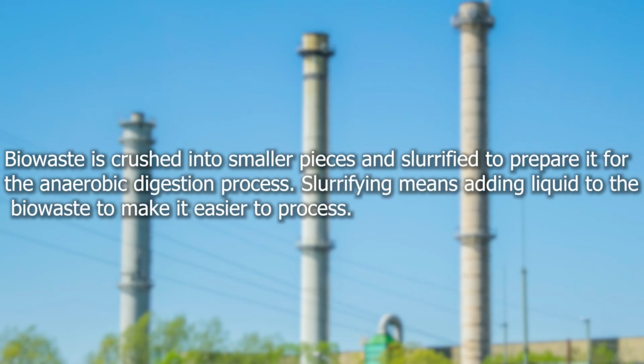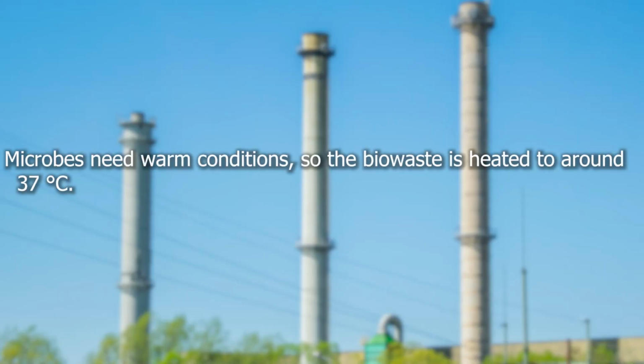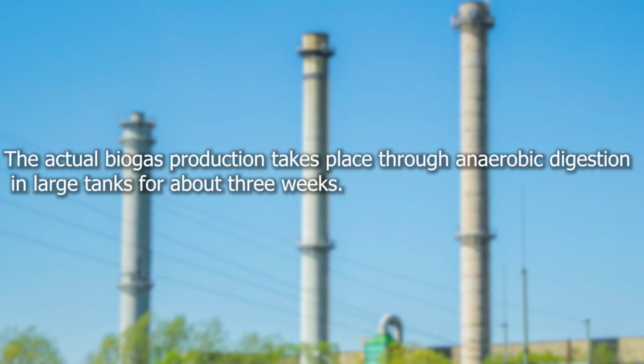The first stage is that bio-waste is crushed into smaller pieces and slurrified to prepare it for the anaerobic digestion process. Slurrifying means adding liquid to the bio-waste to make it easier to process. Second, microbes need warm conditions, so the bio-waste is heated to around 37 degrees Celsius. Third, the actual biogas production takes place through anaerobic digestion in large tanks for about 3 weeks.